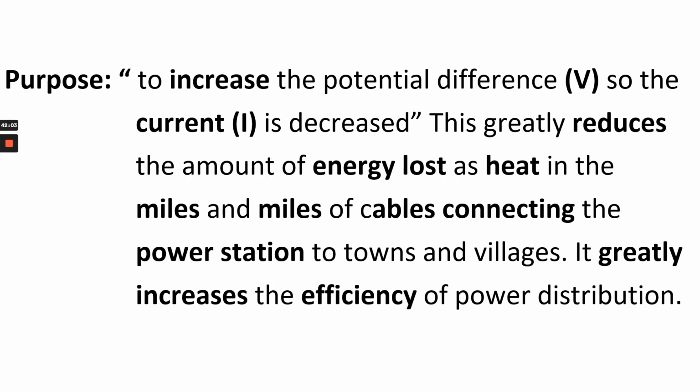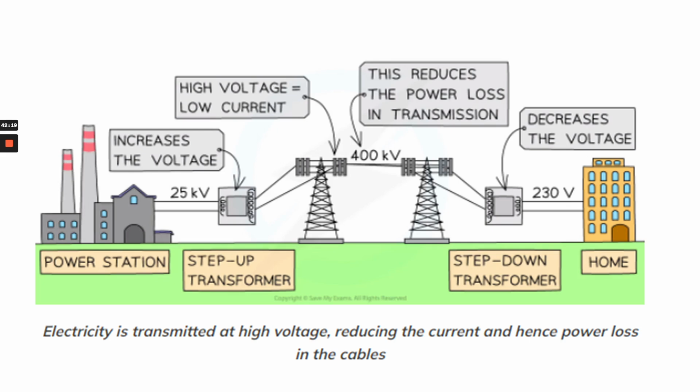Its purpose is to increase the potential difference so the current is decreased. This greatly reduces the amount of energy lost as heat in the miles and miles of cables. It increases the efficiency of power distribution. Here's the maths to prove it, okay? So let's have a look.